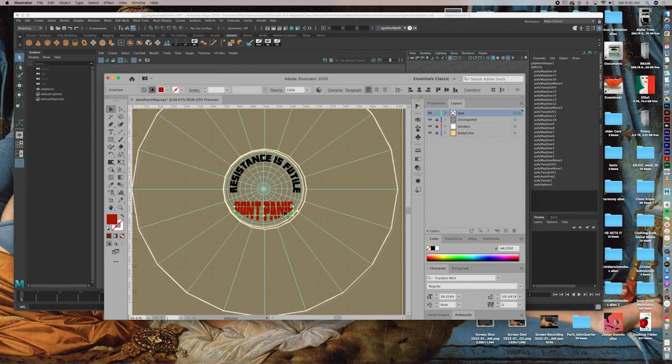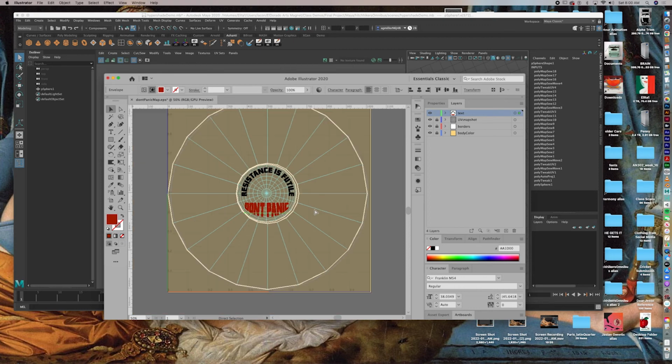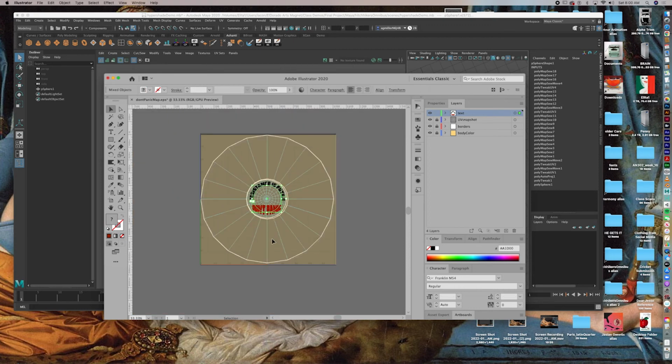I see the UV is a little off here. I'm going to center it anyway in Illustrator, and I'll manipulate the UV to adhere to the map on the other side. So this, make sure I align to artboard. Yes. It only needs to be aligned vertically. Yeah, now I'll manipulate that UV.